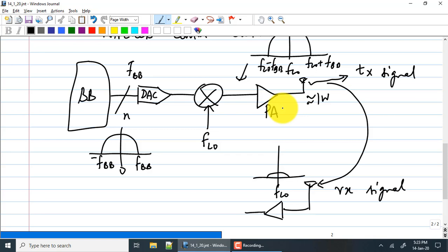If you can imagine, 1 watt corresponds typically to several volts of swing, several hundreds of milliamperes of current. Which means that the current densities in the circuit, or the total currents of this power amplifier circuit, are larger than what you have all encountered so far. So there must be something special about it, and power amplifier design is indeed a specialized area.